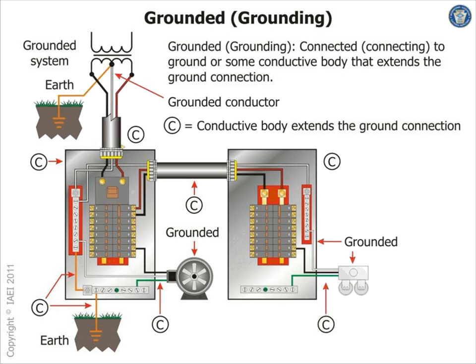So I thought to start with a very simple system, and then I'll go into the sizing. Here's a single phase, which is very similar to a three phase. You started with a grounded system, given to you by the utility, by connecting part of the transformer into the mother earth, stabilizing it. Then they give you a neutral, that's called the grounded conductor, that the code considers the neutral grounded conductor. So I am bringing a grounded system into my building.